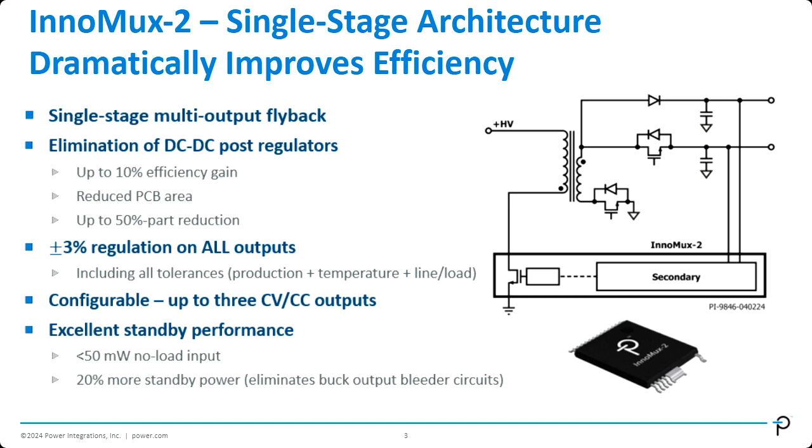48 might be a bit too high, but it really depends on your power allocation between the two outputs. I normally recommend the top output over bottom output to be around 2.5 or less than 2.5 times difference. But if your lower output is just like 2-3 watts, it might be okay. You might have to run the actual design on PI Expert to see if it runs to CCM.